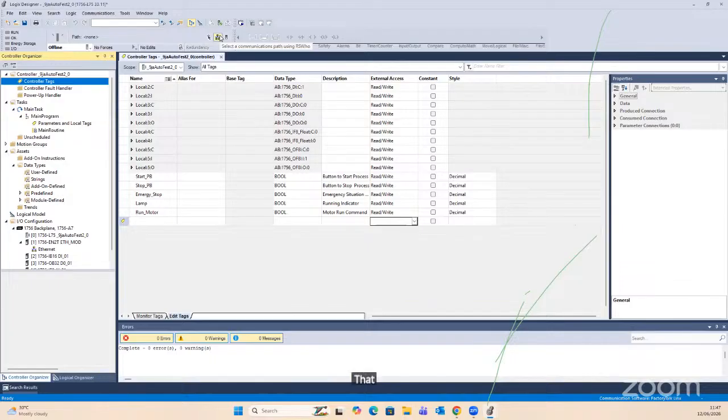That is the first scan cycle. When your PLC starts reading, your PLC goes to OB1 to scan. And that is why when you are calling any other function, you call them from OB1.